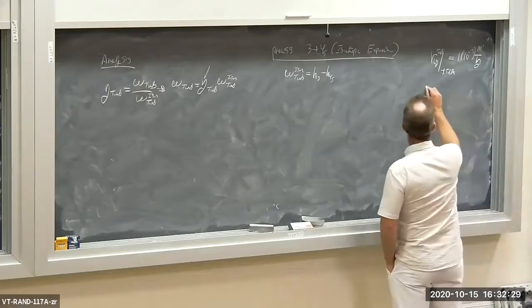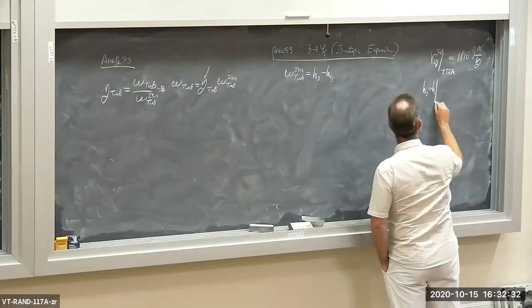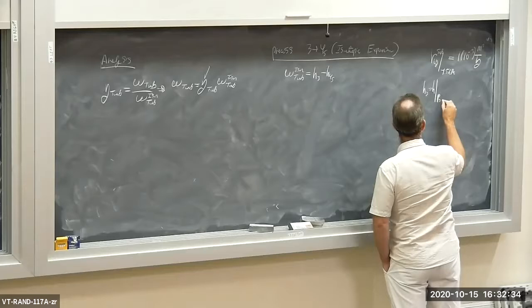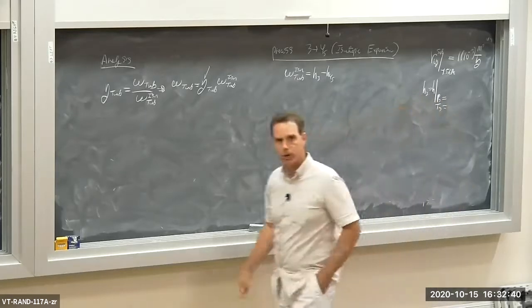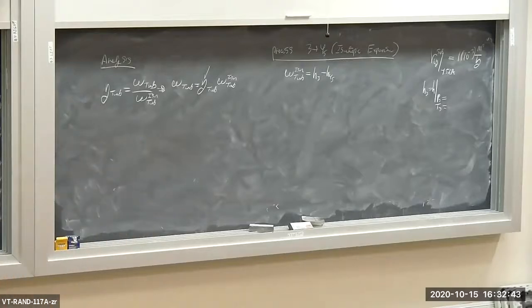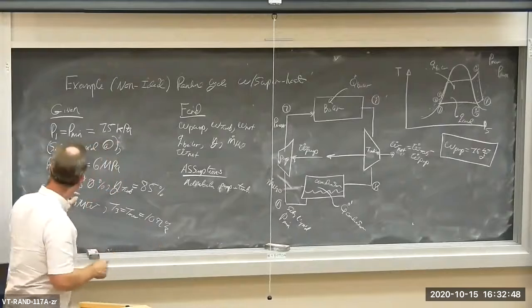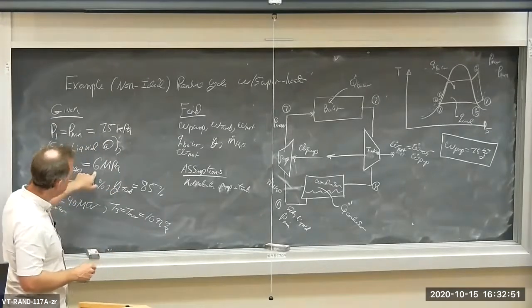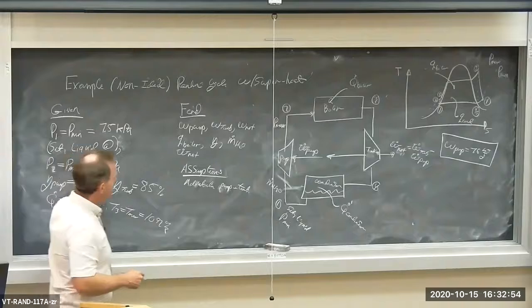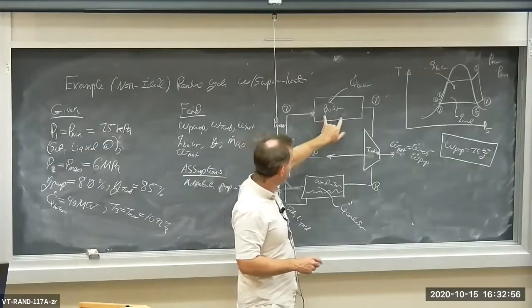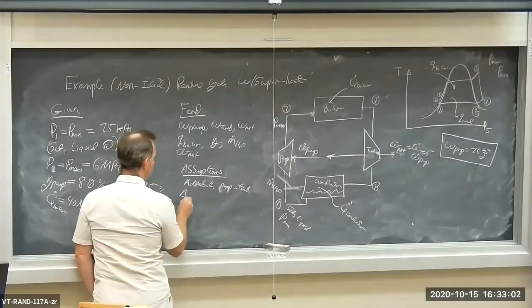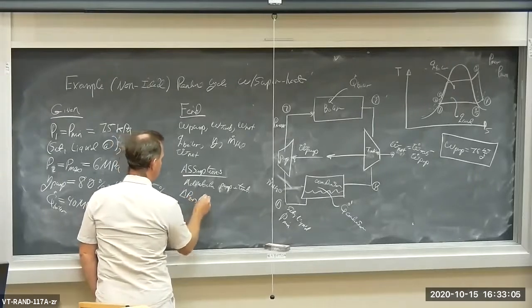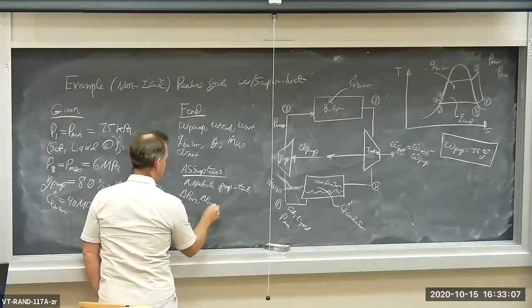Okay, now what's H3? So H3 is H evaluated at pressure P3 and temperature T3. Let's see if I have these temperatures and pressures. At state 3 I have a P2, which is P max, that's 6 megapascals. I don't see any indication there's a pressure drop across the boiler or the condenser, so I'm going to write here in the assumptions delta P from 2 to 3 and delta P from 4 to 1 equals 0.